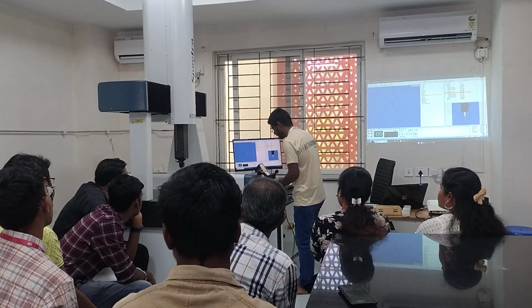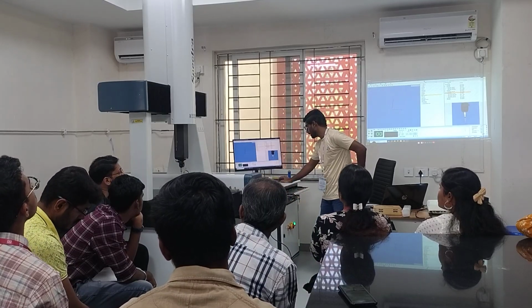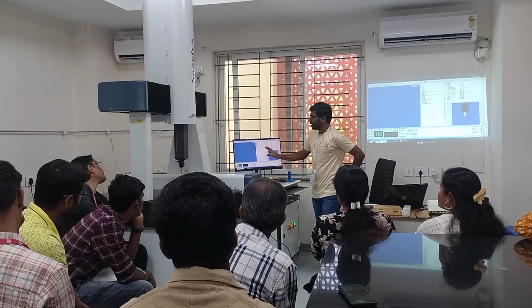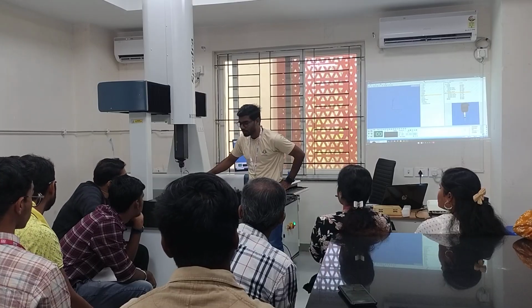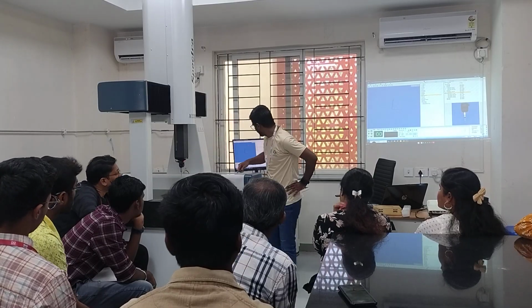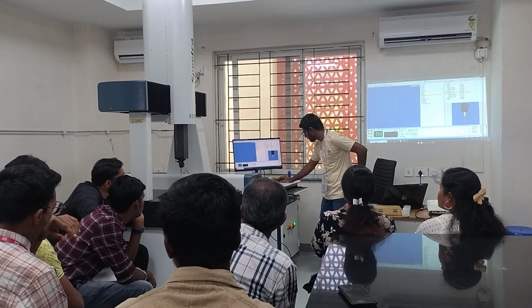Before this, we have to check another setting here, which is the approach distance. This is basically used when you are automating. If I want my sensor to be here, approach distance is how far it should go and search for the body. It cannot go to an infinite place. I have kept it at 1 because I am not going to use any autonomous mode here.